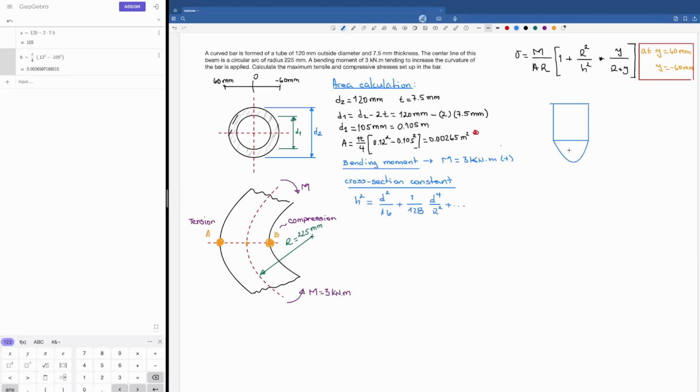Let's imagine that this is a semicircle. Well, I don't know where the centroid of this is. I don't know where the centroid of this is. Then if I want to calculate the centroid of the compound image, the whole thing, there is a rule that we could follow using the areas and the position of the centroid of each one of those known areas. That's going to give me the centroid of the compound area, or the combined area.